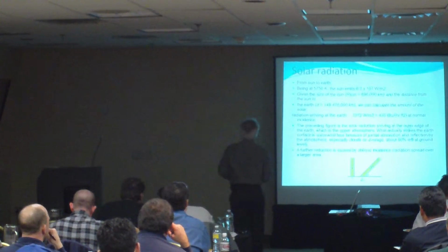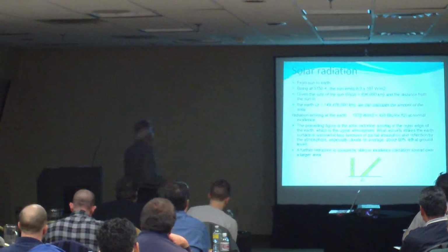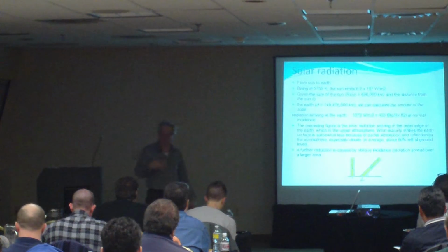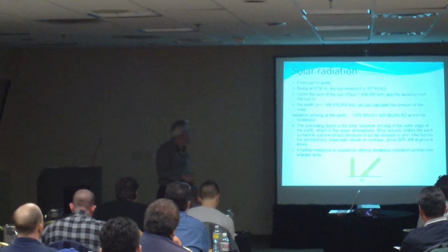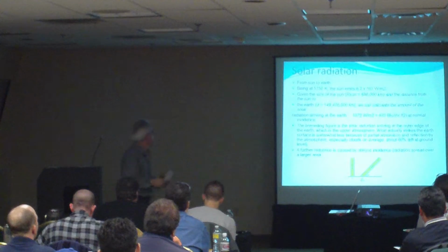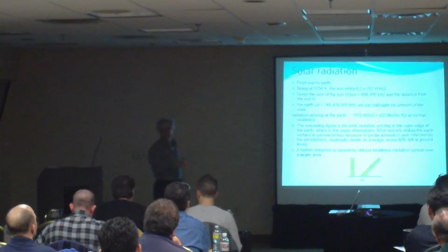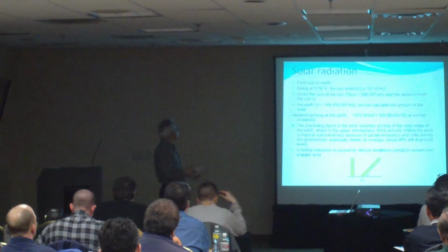All right, so the sun, being approximately 6,000 degrees, emits a lot of watts per cubic meter. But in order to reach the earth, you have all kinds of problems up there. So approximately you're getting about 1372 watts per square meter, which, for some of you who are in the air conditioning business and like BTUs, since somebody asked me the other day to talk about BTUs rather than watts, is about 435 BTUs per hour square foot, okay?